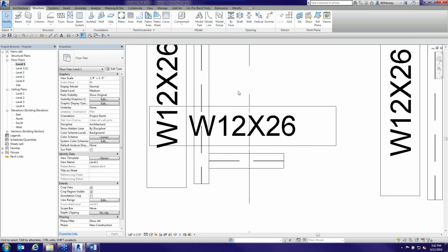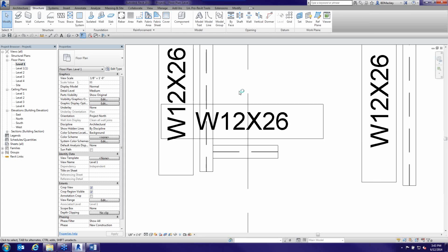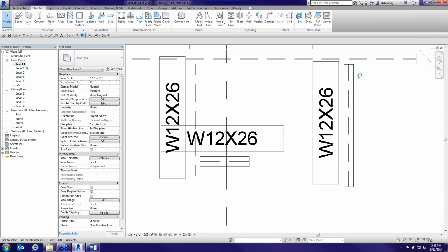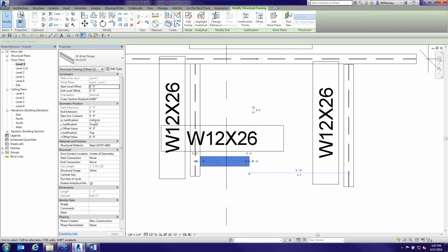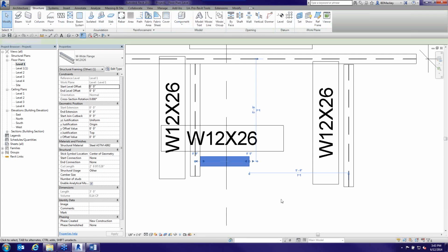So to me, for my structural engineers, especially doing a lot of wood frame, that was huge when I found that out when 2015 came out. Well, man, now you can have your default setback 0 for wood or ½ for steel, depending on the type of object you're modeling. So I thought that was a nice feature, being able to change that start join cutback or end join cutback. Now that it's been connected, I don't get that, but getting that started in there was really big when I found that out. So hopefully that will help a lot of structural engineers out there.